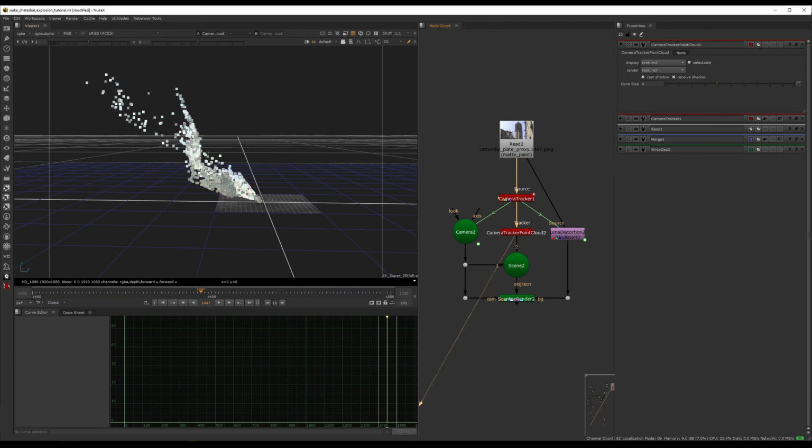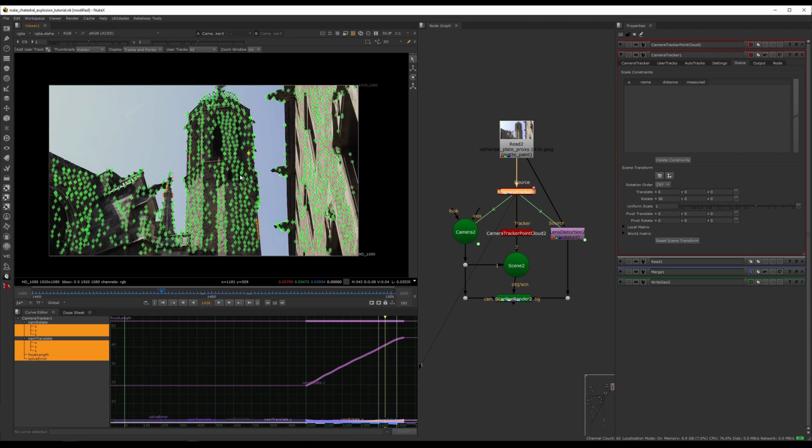We don't have the ground, because usually, if you have the ground, and I'm pressing tab, by the way, to go between these two views, you could just select these, right click and say ground plane, and it would do that for you. But because we don't have the ground plane, I kind of eyeballed it and 30 was kind of perfect.